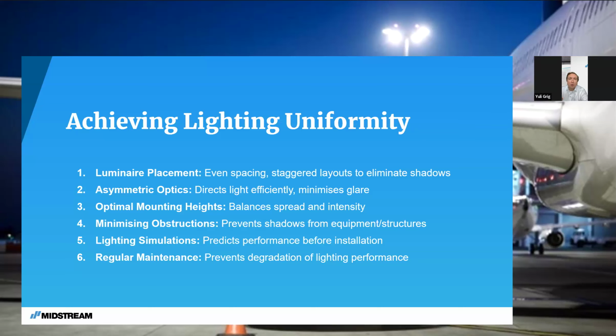So that's a good point, because we didn't cover this in the slides, but we are asked a lot whether the requirements for 20 lux and 0.25 uniformity must have the aircraft on the stand or clean and clear. No, it has to be clean and clear, also because the moment you place an aircraft on the stand, you will 100% have some points which are even 0 lux if they are directly under the plane. So it would be physically impossible to reach the 0.25 uniformity. Let's say that maybe we didn't mention the uniformity a lot.